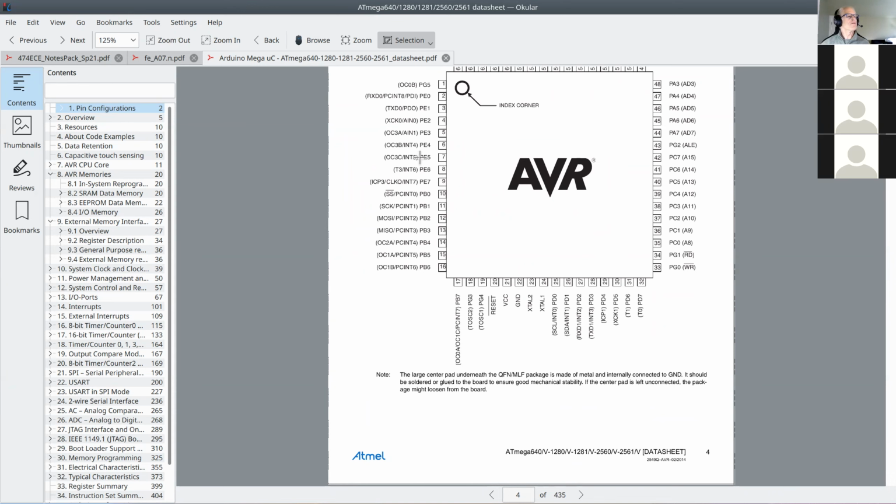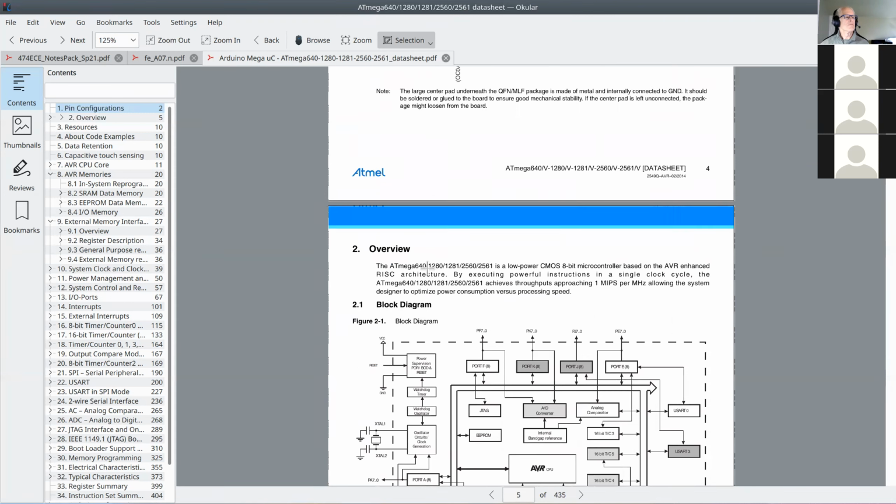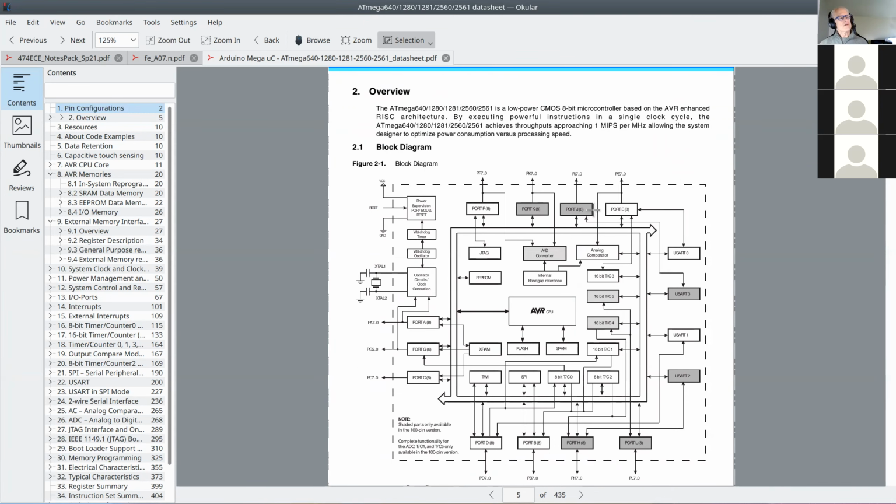All of these have port pin designations, and they also have separate names, and we'll see what those mean. So each of these ports typically has multiple functions. Like this USART, this is a serial data communications interface. There's 3 of them. Well, there's 4. There's 0 and 3. And when they break them out like this, it means they have slightly different features. And of course, serial communication is an external function, so it needs pins. So it can use the pins in port J.